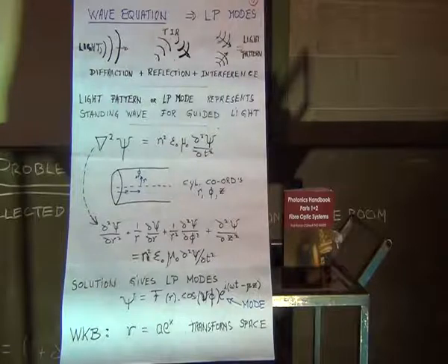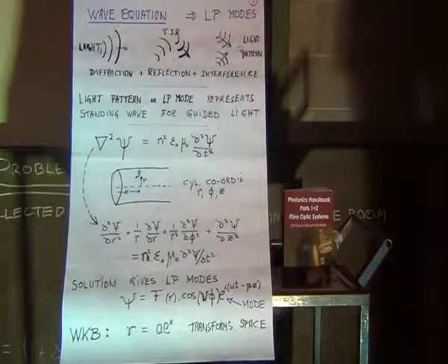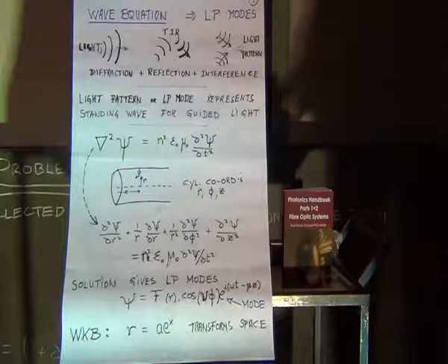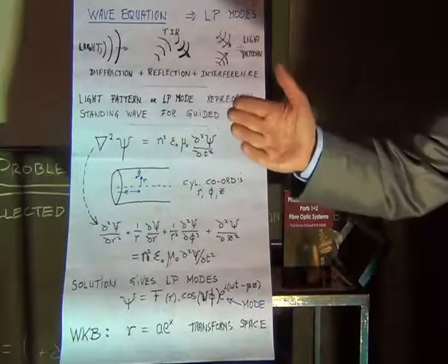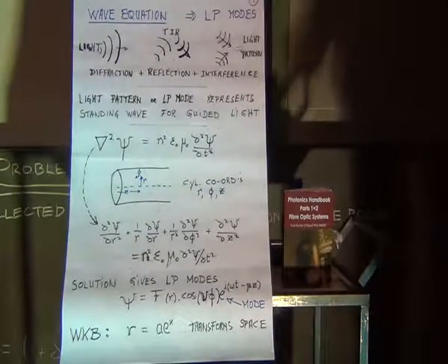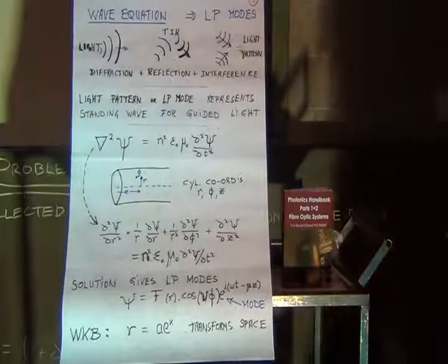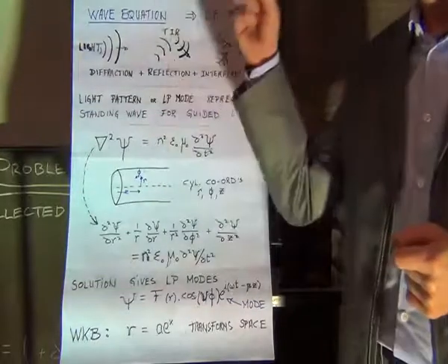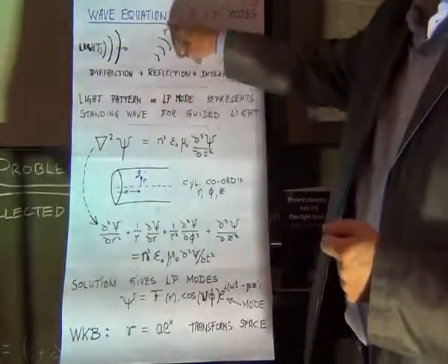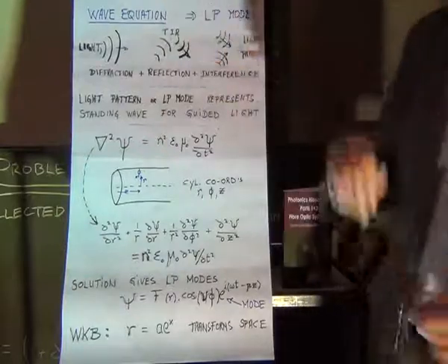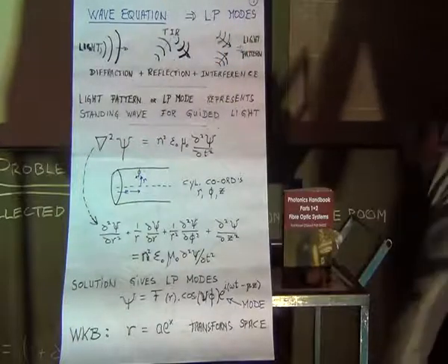And we took a kilometre down the axis, and then we took the critical angle and worked out how far that would be. Okay? And that gave us so many meters per kilometre. The slow rays travel so many meters more for every kilometre of fibre. You just divide that number of meters by the speed of light and you'll get the number of nanoseconds of dispersion per fibre. Right? But the problem with that was it was very primitive. All we were taking into account was total internal reflection. Okay?